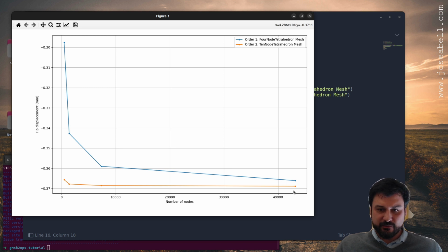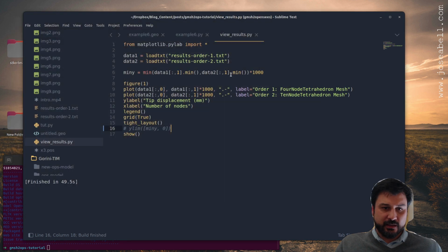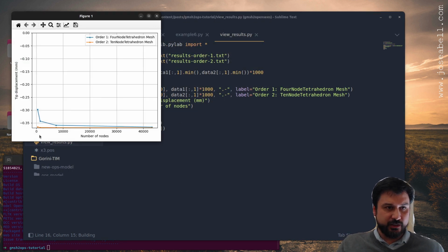So in this case, my converged mesh will look like this. Now the vertical scale is not starting at 0. If you want to see realistic values, this is what they look like. That's 0. So they're still a bit far away. That might be a percent difference. Maybe that's 80% of this value. So you're 20% off in this solution over here.